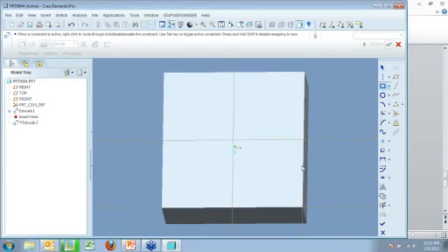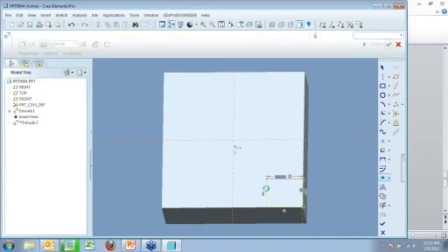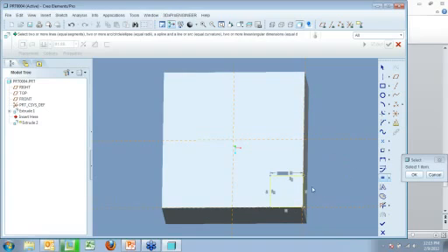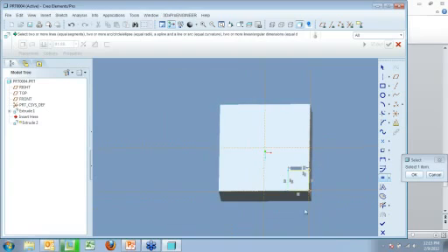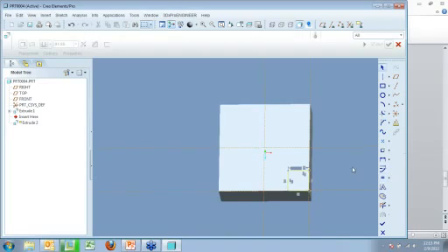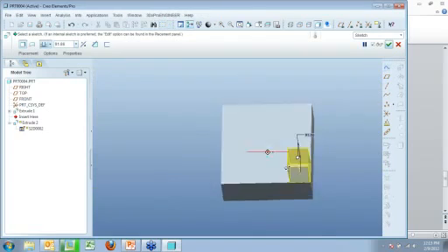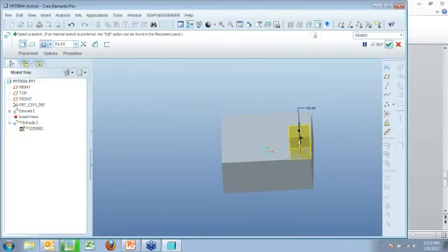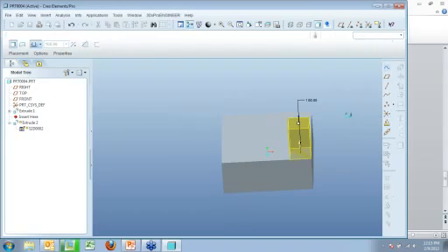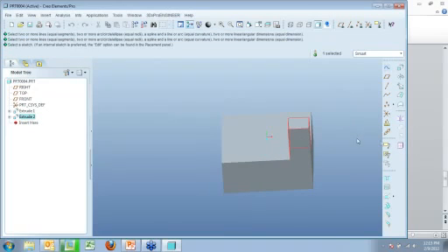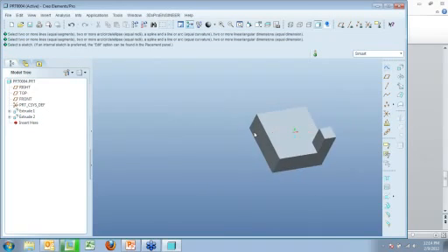So now I'm going to go in. I'm going to create a square that snaps to these 2 points. I'm going to go in and make it equal again, which I could have done without; I could have dragged from that corner up and done some on-the-fly constraints there, and that would have worked just as well. Now, again, I have to come down here and click this check mark, go in and drag it to where I want it, or we'll make this one 100 tall as well. Excuse me. So there's the part I'm going to make.